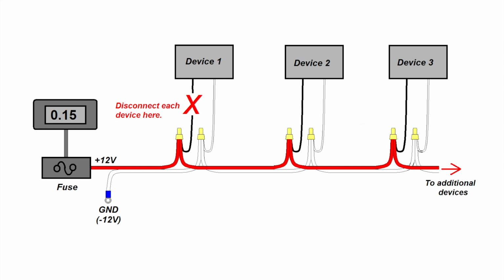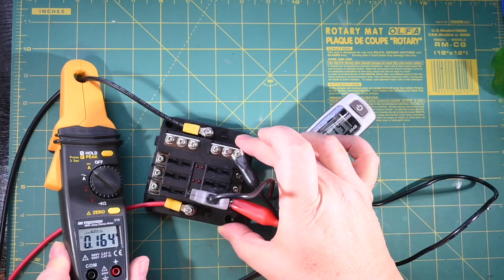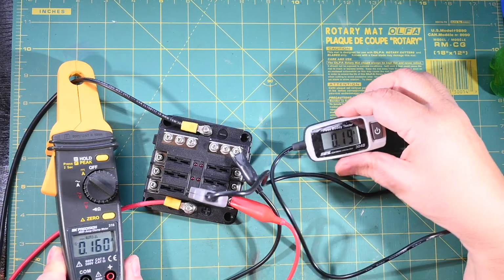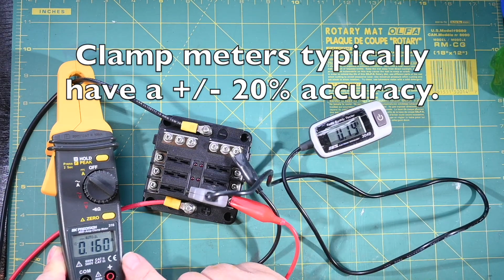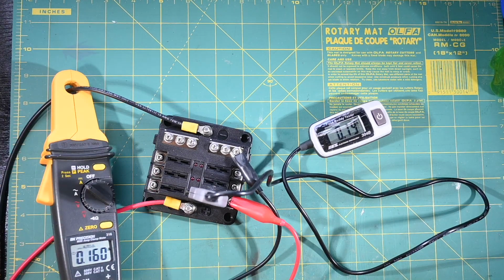At some point, you may have to simply disconnect the device you suspect. One tool that may make this task easier is to use a mini clamp ammeter such as this BK Precision 316. You just put it around the lead and you can see we're measuring about 160 milliamperes, which we're actually drawing about 199 milliamperes. So these are not 100% accurate, but at least get you in the ballpark. And you can actually put it on either the ground side or the positive side.